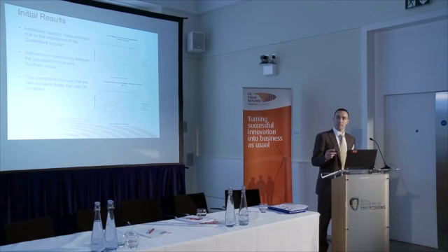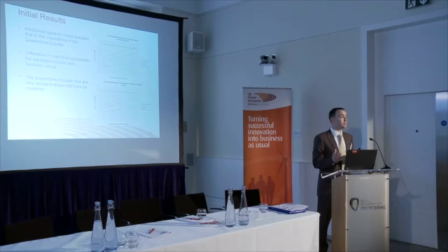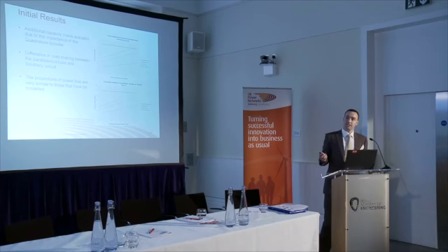The only noticeable difference is that the Swaffham line appears to carry more load than our models would suggest. The net impact is that the load sharing between the 3 circuits is actually better than we thought, with the net effect that, in theory, the Downham Market circuit could carry more load at this position.